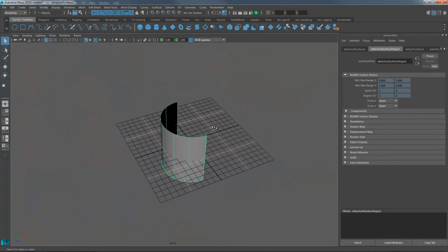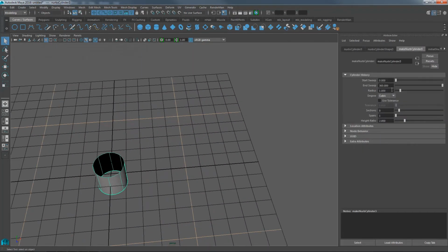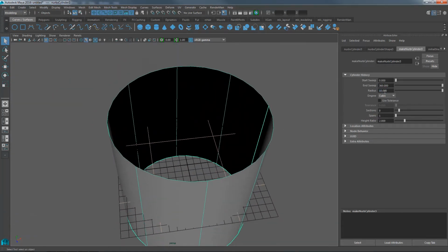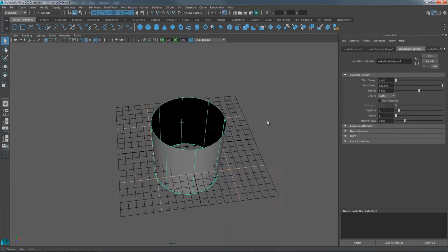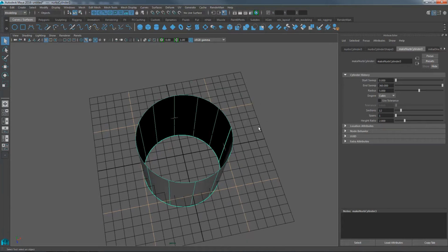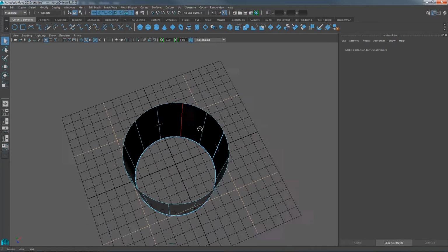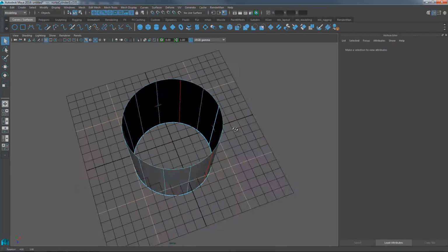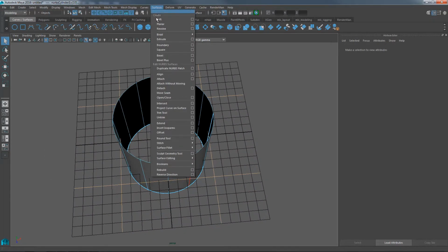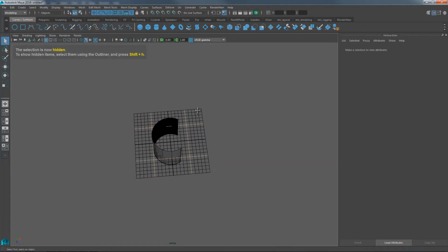So we need to change what we're doing with this inside cylinder. Just hide the one that you have here and bring in a new one and set its radius to 5, so its total diameter is 10. Its number of sections will be 12, and we'll go with 12. We're happy with that. Then instead of the center isoparm, go one off center. See, those two. And then detach. Then take that piece and hide it.